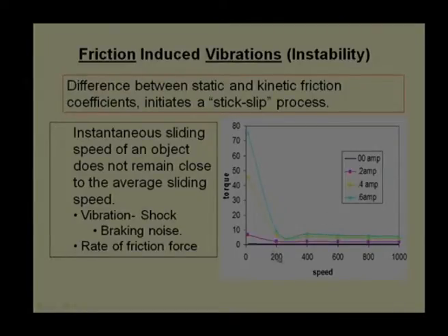Particularly when the operating speed is nearby 260, say within a range from 200 to 300, there is a possibility of friction instability. The coefficient of friction does not remain stable. It keeps changing from one value to another, and that is dangerous. That makes a lot of noise, which should be avoided as far as possible.